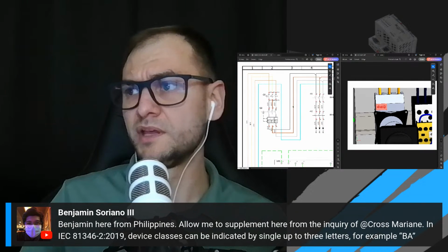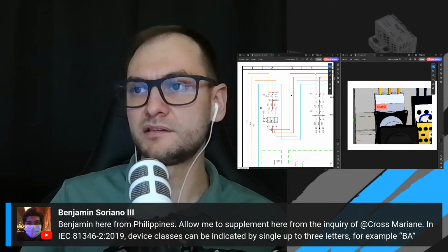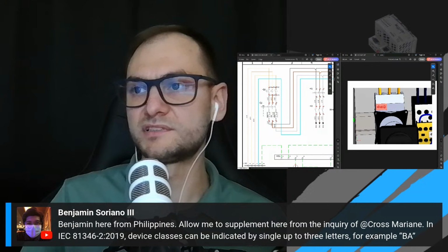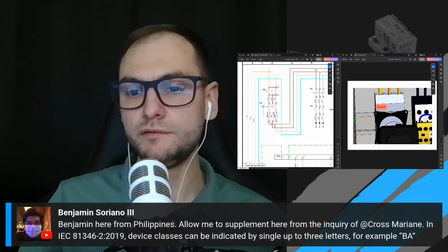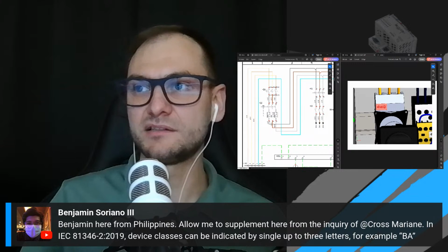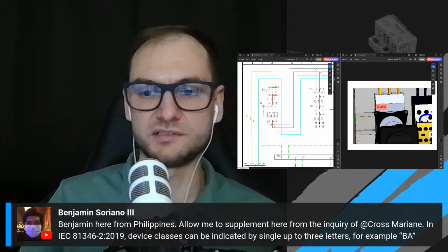For example, the contactors are called with K, the disconnecting devices, the circuit breakers are named with Q. But if you want, you can extend this name up to 3 letters. For example, QA1, this is no problem.